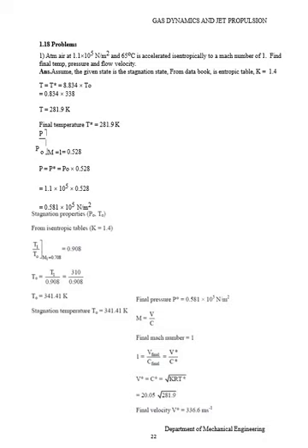From the data book, isentropic table, K equal to 1.4 or gamma equal to 1.4. Therefore, T equal to T star is equal to 0.8334 T naught, therefore T equal to 281.9 Kelvin. The answer is 281.9 Kelvin. So it is the final temperature. Then find out the final pressure.